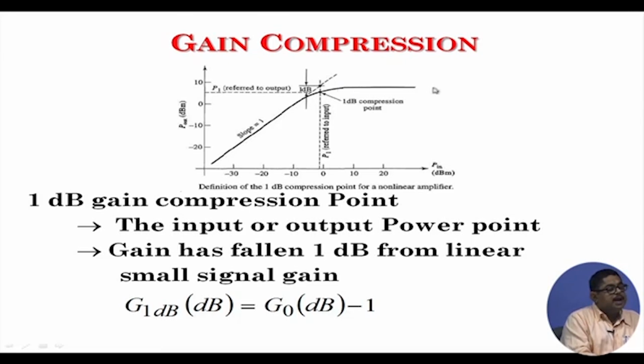Obviously, when it is flat, I know that it is a nonlinear thing, it is saturated. But here, people have decided that we will not say it is nonlinear here; we will say that here it has become clearly nonlinear. This point is called the 1 dB compression point.